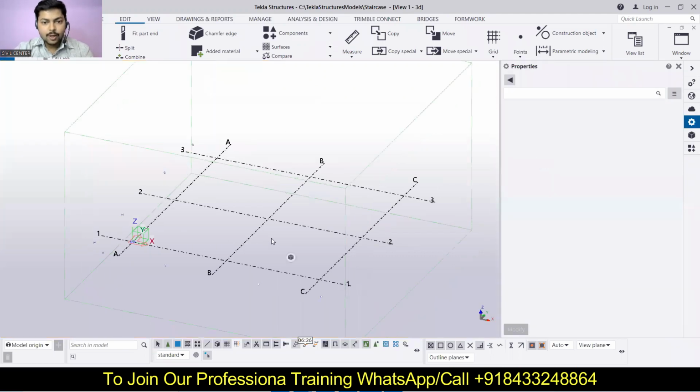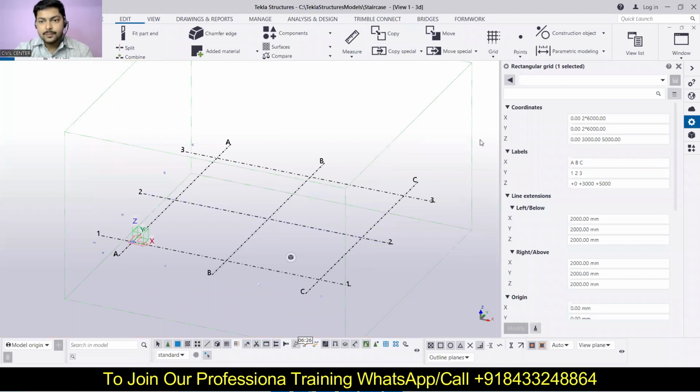First of all, double click on the grid lines, and over there just modify this grid line. To modify that, we have to adjust the x, y, and z coordinates of the system. So the first thing that I have to do is go for this one, that is the z direction. In that we have 3200 over here.